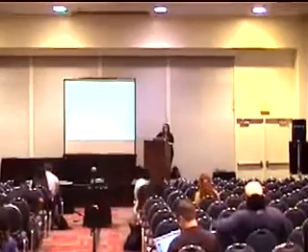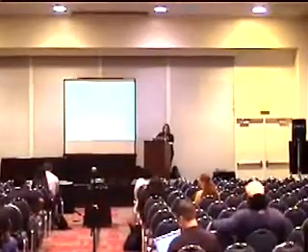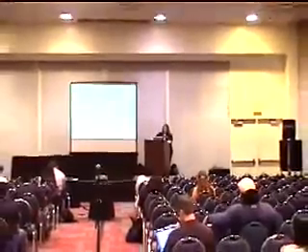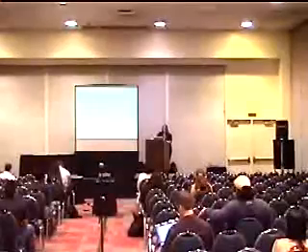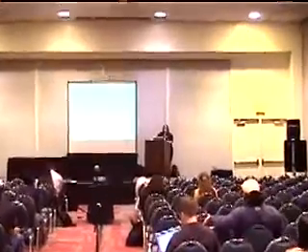I have a general rule of thumb that I don't like it to exceed 10 meters, but in all reality it's generally enough. If you've got a really strong signal and you're using, say, a 50-50 and it's still enough to traverse the network and be good data, and then you're sending 50% of the light to the monitor, certainly you're going to be able to extend a longer distance on the monitoring side. But again, I've probably seen it go 30 meters, 40 meters, but you are taking a lot of cable losses, so you're still degrading the light at some point based on that distance.